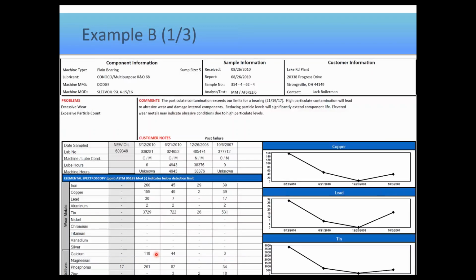You know, it's typically an additive element, and if I don't expect this additive, well, then I've contaminated it with another product that does have this additive. So I'm thinking this is probably a cause, right? Wrong lubricant? Certainly could explain why I have wear. But carrying on, I look at phosphorus next and again decide this is abnormal.